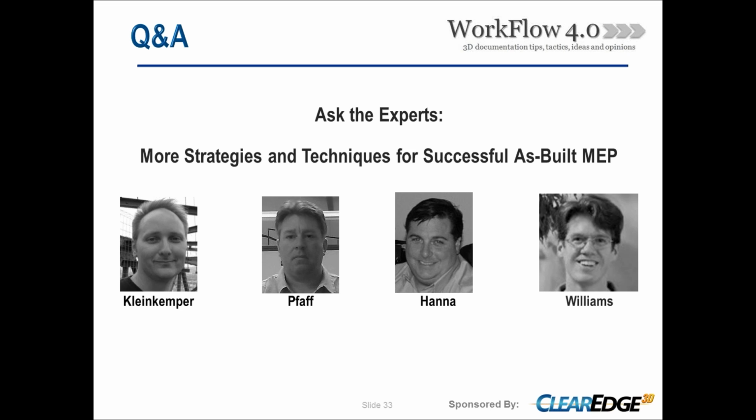Larry, you're Mr. Revit. Do you have anything to add to that? No, he did a good job. He pretty much nailed it on the head. I thought about adding the fact that Revit only goes out a certain extent. I believe the number is like 2 miles, and then you're going to have to break it into a separate project. But aside from that, I like the way Mike put it. Thank you.